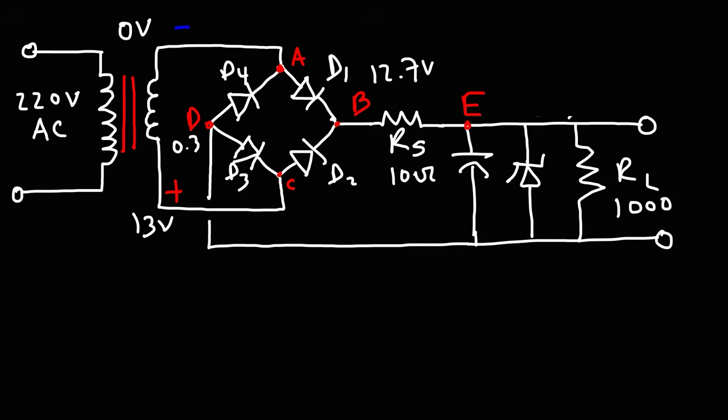And it's designed to work in reverse bias mode. Now, the zener voltage that we want to have for the zener diode is 12 volts. Ideally speaking, we need to set the right current flowing through it so that the voltage drop across the zener diode is 12 volts. Now, let me take a minute to explain how this is going to work.